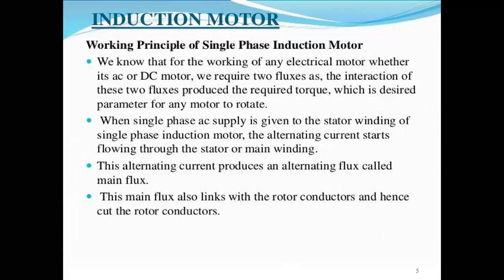There are lots of applications of the induction motor over the DC motor because it has low cost. It requires less maintenance. It is simple in construction. It is reliable. Its power factor is also good, and we can call the induction motor self-starting because it does not depend on any other device. That's why we can say it has lots of advantages over the DC motor. So here we will see firstly how the single phase induction motor works.